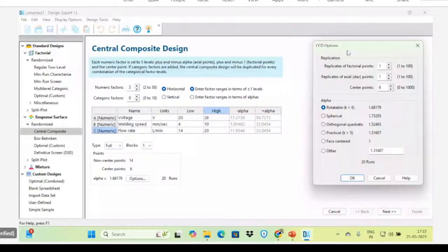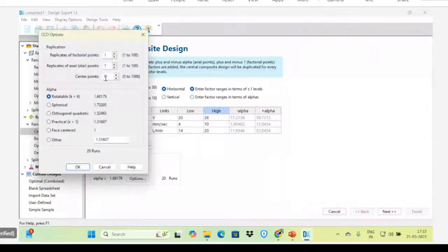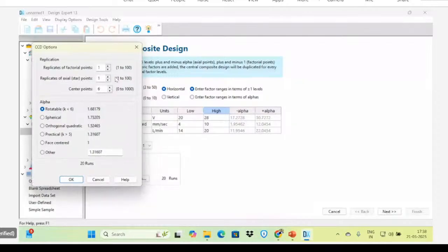So that's why it is central composite design. The central value has the highest priority, getting the majority of the process parameter runs. I will show in the Design Expert design of experiments. Then the alpha value you have to keep as 1, because we are considering a central composite face center design.